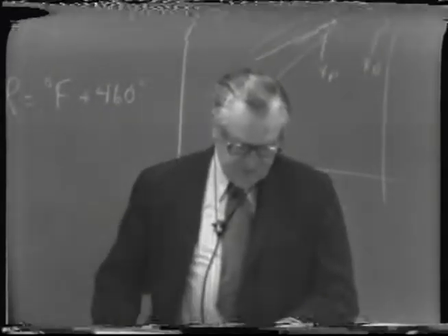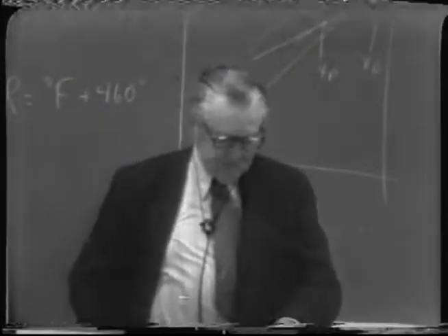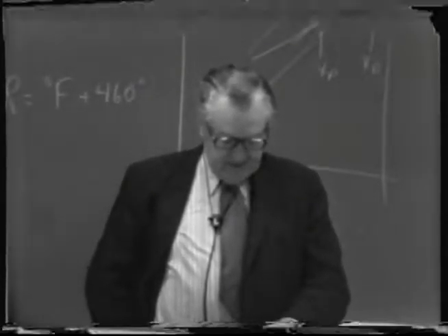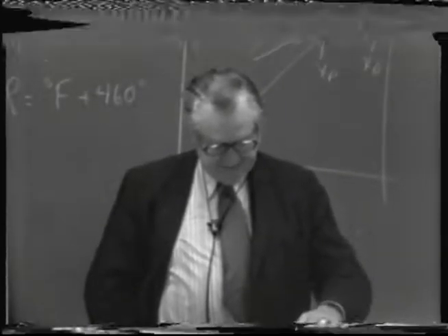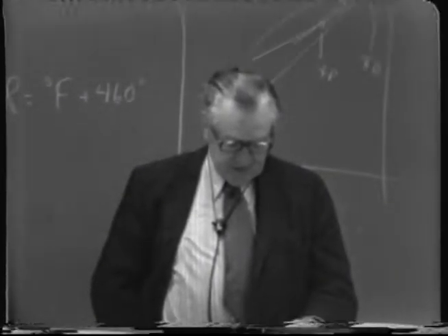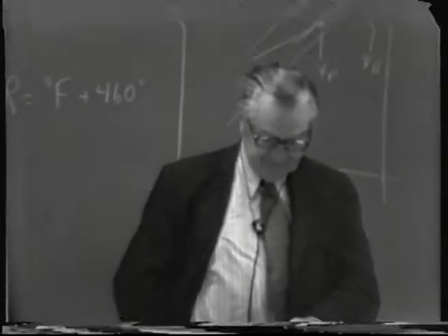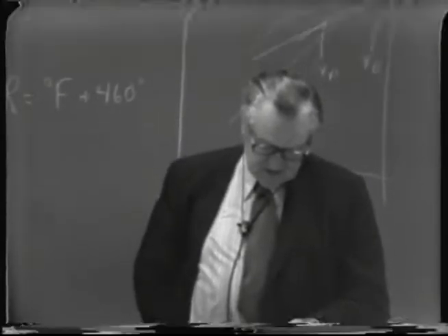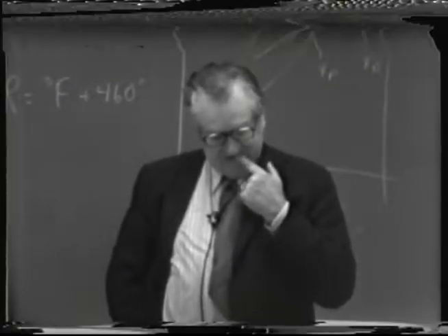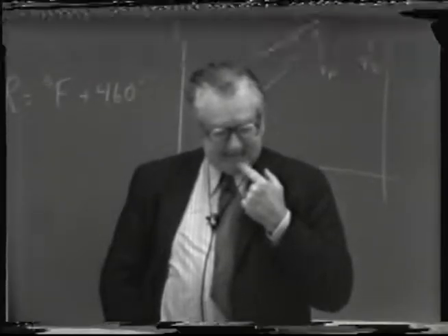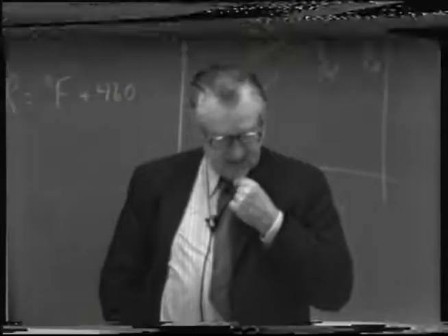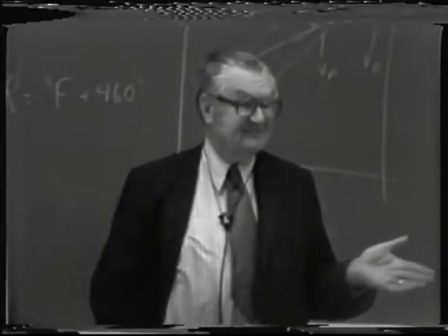So again, converting that vapor rate of 1,396 moles per hour over to cubic feet per second, we come out with 193 cubic feet per second. Applying the same type of formulation to calculate the diameter D, where the allowable vapor rate was 4 feet per second linear rate, it comes out to be 7.8 feet diameter. That's slightly less than the diameter of the rectifying section as we calculated here. But anyway, it's still realistic.